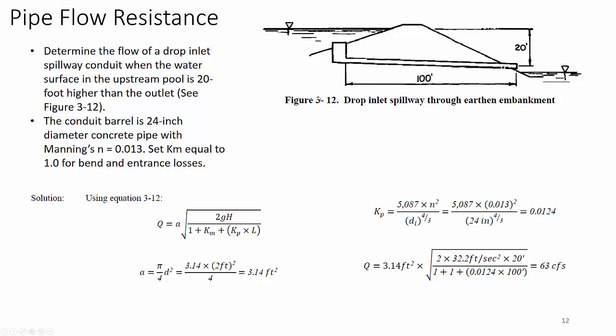Minor losses are part of pipe flow that you learned about in hydraulics, and you can look these up in any hydraulics textbook about losses. But generally, you consider a minor loss of 1 for just a 90-degree bend. And most of the time, that's as complicated as it gets for hydrology, because we're not building complicated conduits for pipe distributions. That's a hydraulics problem, not a hydrology problem.